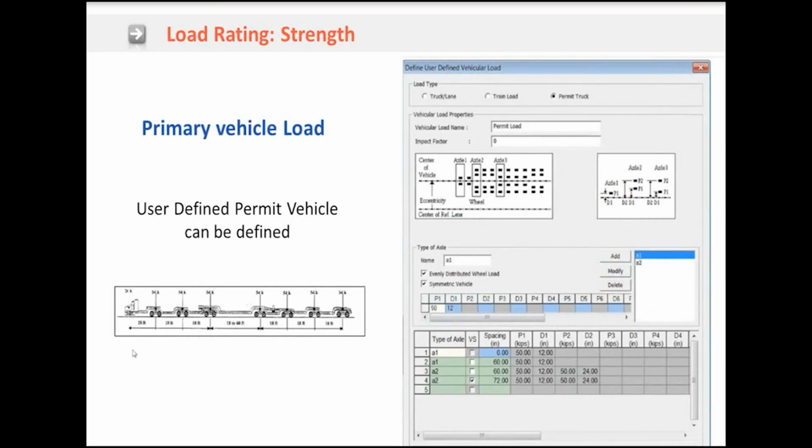This example is an example from Caltrans, which is just a truck that they didn't need to run on the bridge. So we can model all these, regular or irregular shapes, symmetry or asymmetric axles and wheels. As you see here, we can just simply do that. We are defining the loads for axles and the wheels separately, and then we can just get the combination. So technically, based on this model that we have available on MIDAS Civil, you have no limitation on modeling the permit trucks for running on the bridge.